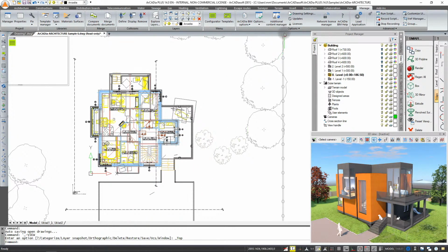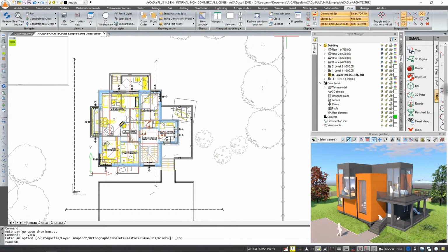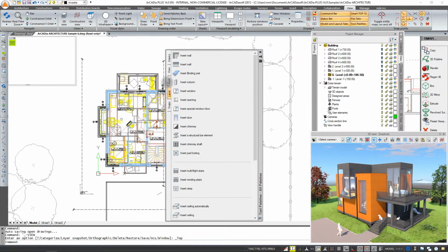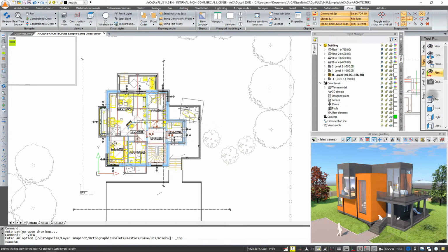We can change the interface not only in terms of colors, backgrounds, and the appearance of toolbars. Here we have the option of both using toolbars because we can switch to the classic view. We can of course stay in this ribbon system, but we can leave one ribbon and define it ourselves. So here, setting the program to your own needs is quite extensive. We also have the option, if someone has a fairly wide monitor and not a tall one, that is a panoramic one, to find all the tools on palettes, which we can also define ourselves, and by using the palettes, roll up these ribbons on top so that we have more space. And as I mentioned, when it comes to the command bar, we can enter English commands with an underscore, aliases, shortcuts. We can define everything with such a customization window.